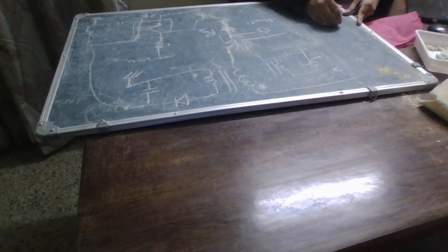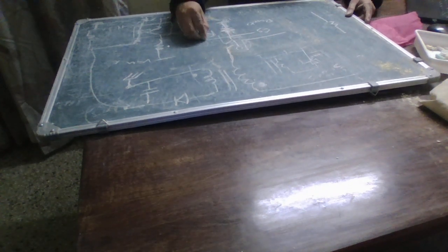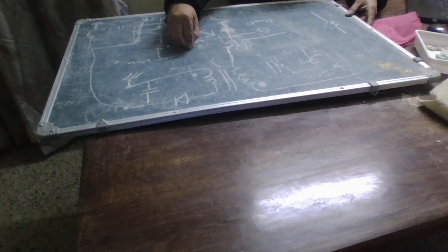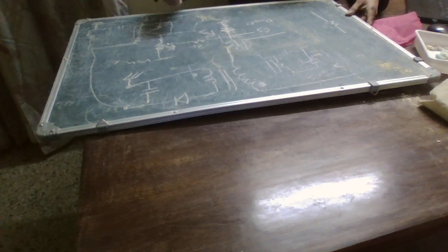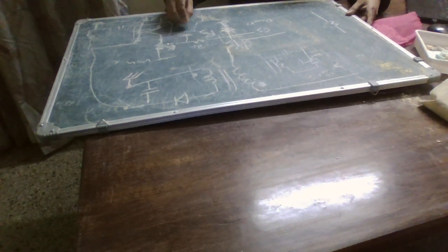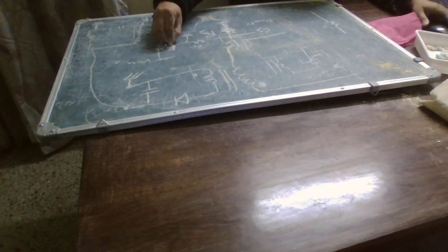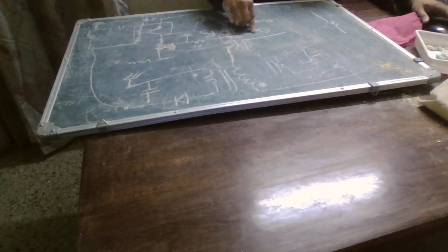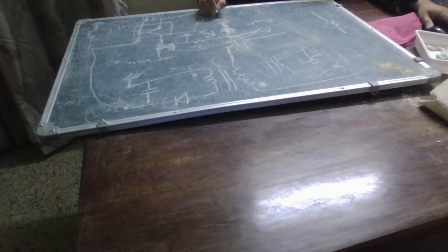That means I have just mentioned an RS here. Now I mentioned that I would need a low pass filter. So we are going to have an RS here, and a low pass RF here. We are going to have an RSL if an external slope compensation is required. We have a capacitor here, and it forms a low pass filter. This output is going to go to the CS pin, not directly, but through this LPF.